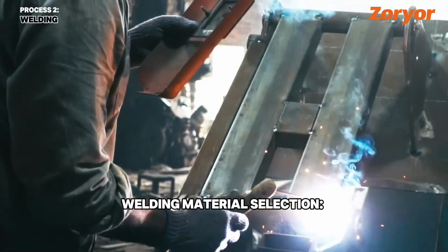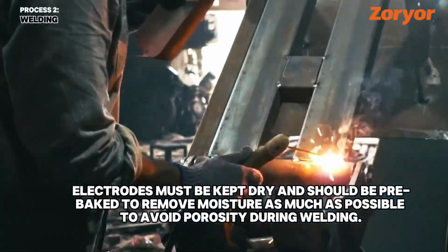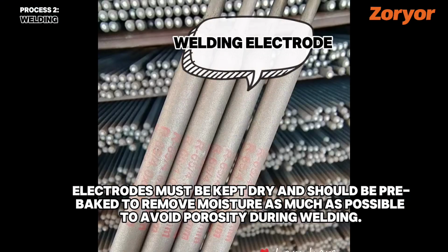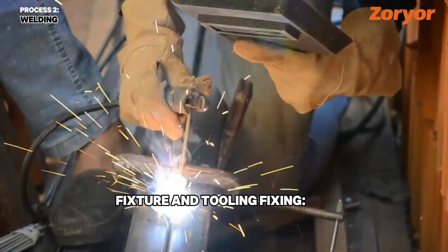Welding material selection. Select electrodes or welding wires matching the material of the bed frame. Electrodes must be kept dry and should be pre-baked to remove moisture as much as possible to avoid porosity during welding. Fixture and tooling fixing.